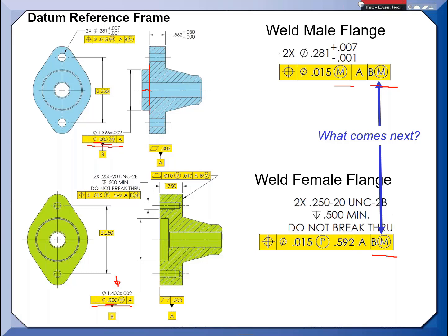Now, if I didn't make those at those values, are these two features going to fit together? If I have a diameter at 1.398 and a hole at the same value, probably not. But what I'm hoping is that manufacturing winds up centering their processes. So it's related to process capability, and I'm taking a risk. Now, I have done this on thousands of parts.